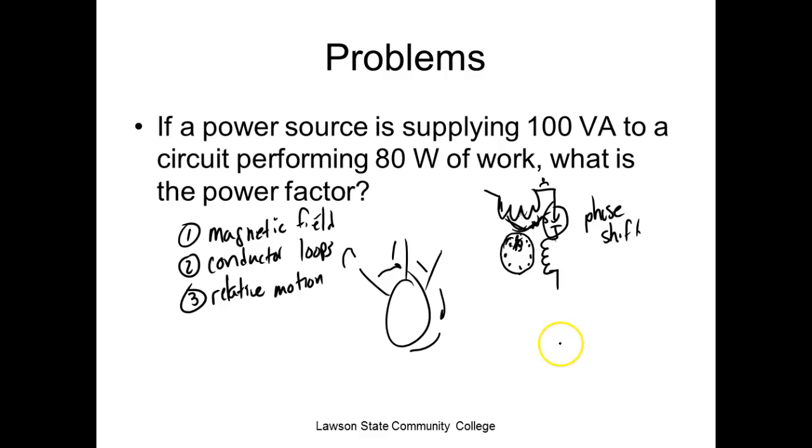We have another motor that we call a split phase motor. That's an induction motor, and it uses a lot of inductance out here on the start winding. Now these guys don't have as good starting torque as a capacitor motor, but they're a lot cheaper to make. So your stuff that doesn't require a lot of starting torque usually uses what we call a split phase motor, but anything that requires a bunch of starting torque is going to use a capacitive motor.